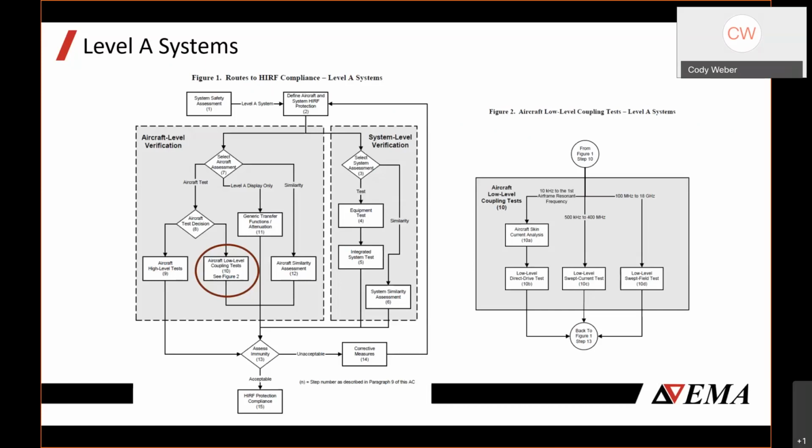And so it's circled in red, and it's the aircraft low-level coupling tests, which in my experience are perhaps the most common aspect for understanding the environmental response to your aircraft to the HIRF environment. And so there's a subsection breakout of that step 10, which is shown on the right in figure 2, and that there's a few different ways to characterize the responses of your aircraft. One of them is through a low-level direct drive test, and this is dedicated towards understanding the current response on your cables. There's the LLSC, the low-level swept current test. Again, this is dedicated to understanding the current response on your cables.